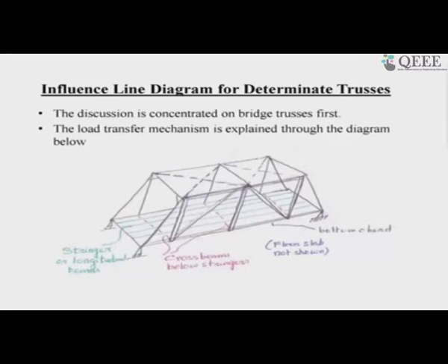Bridge structure is different from the beam in the sense that trusses are basically plane trusses mostly. Plane trusses are mostly used in road bridges or railway bridges. Space structures, such as space trusses, you will see in airport terminals and others, where there are big space trusses many times. Sometimes there are plane trusses too. So, the plane truss is most popular. There are two plane trusses on both sides of a bridge connected by the cross beams, and the cross connections.